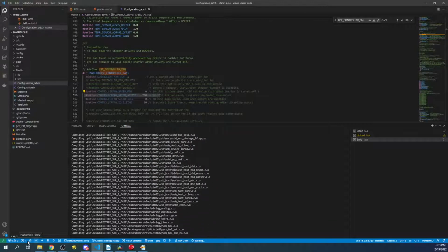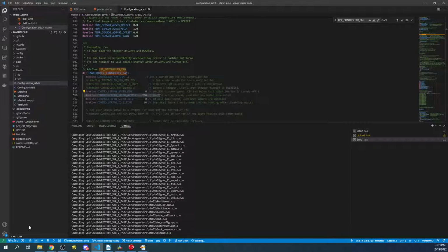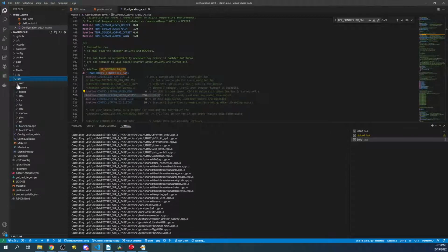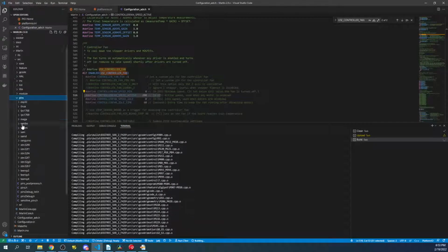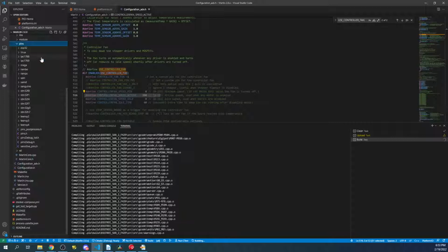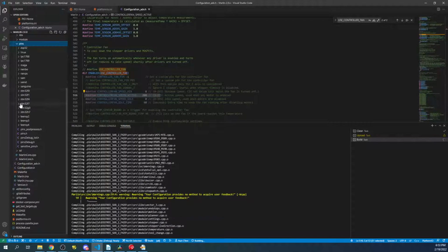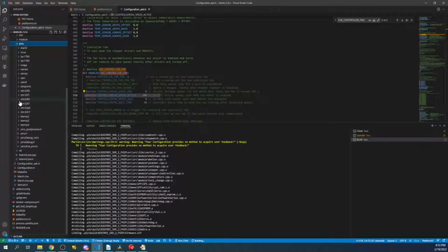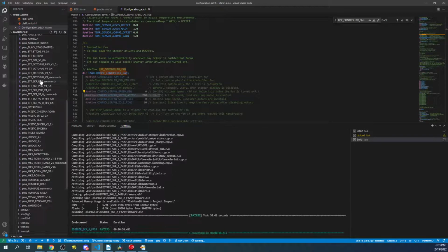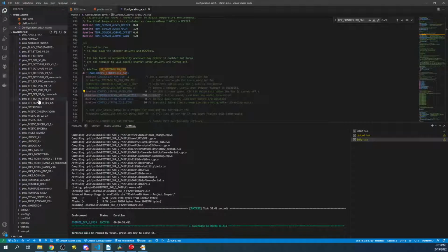Yeah, you can move from port to port, Battle Bunny, by using the pins file. So if you've got a burned out E0 port, what you're going to do is this. You're going to go to source, pins, and then I don't know which board you're working with. I'm guessing that maybe you're working with the SKR2. You'd go over here and find it, and in this case you can see that there's an SKR.